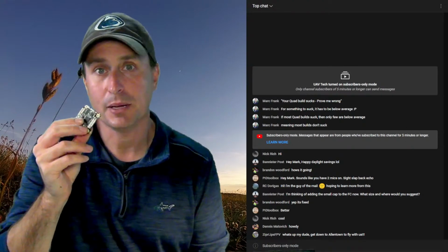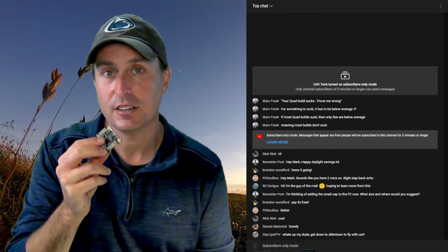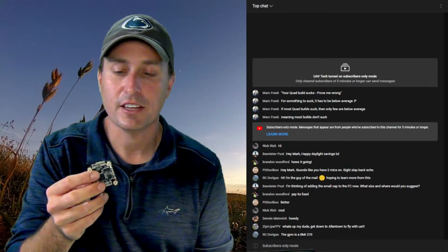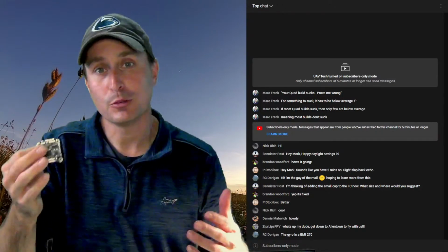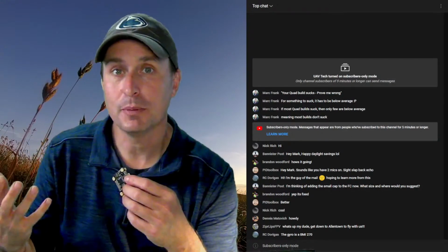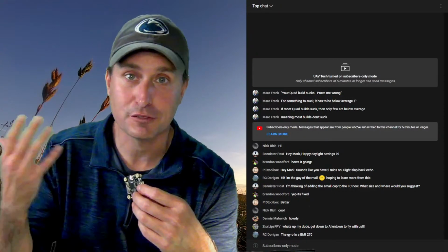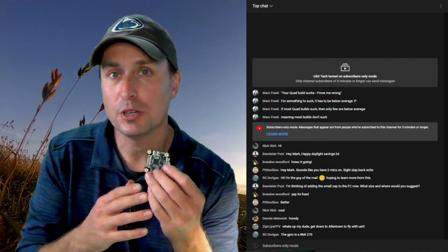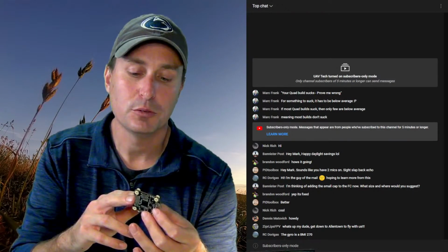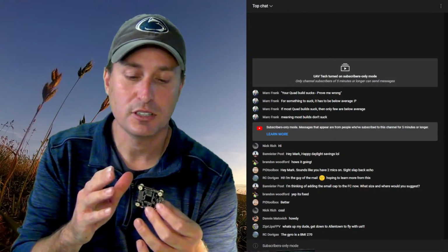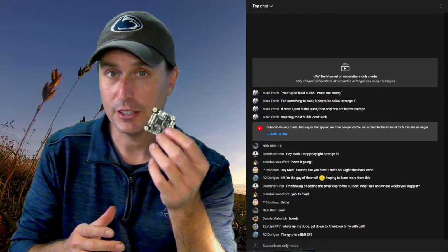And the electrolytic capacitors that you might have, although it's not listed very often, they have a lower voltage threshold. So you can kind of do two things. If it's your run-of-the-mill capacitors you have for higher voltage, like a 25 or 35 volt capacitor or 50 volt capacitor, those would do no good on the 5V or 3.3V rail. For those, you wouldn't need to necessarily have a 1,000 microfarad capacitor on your flight controller itself.